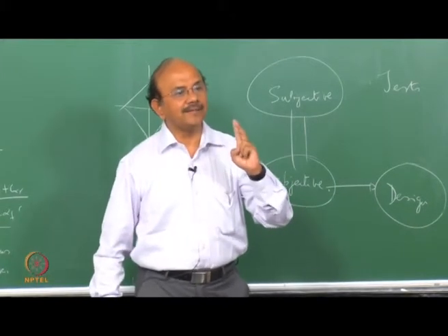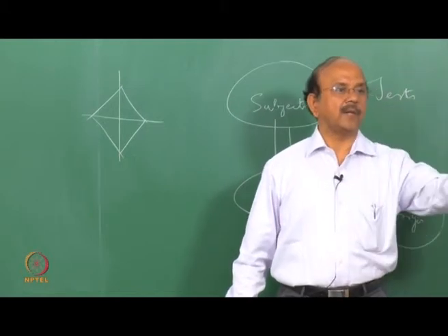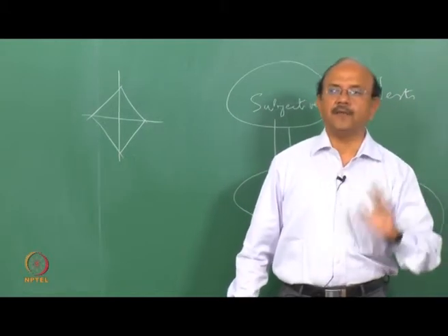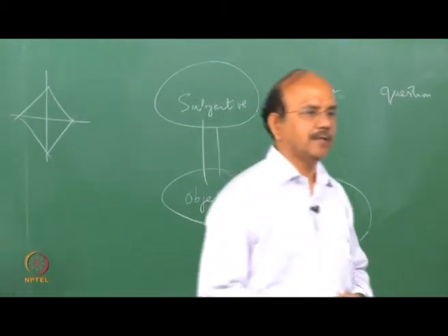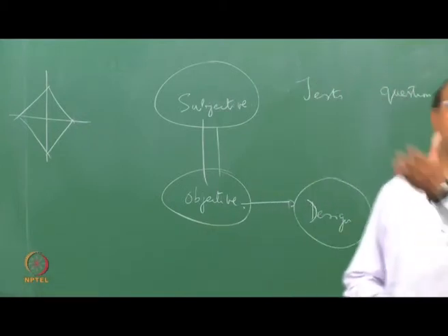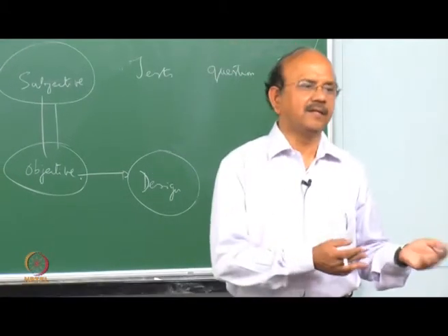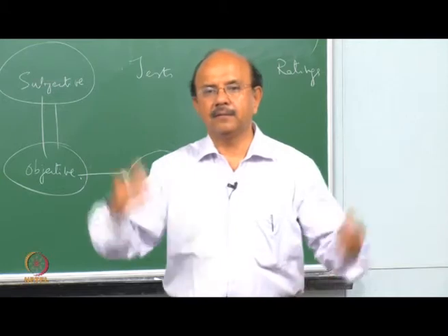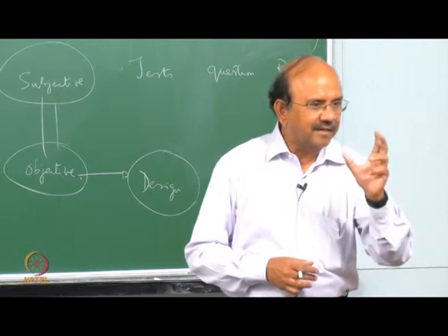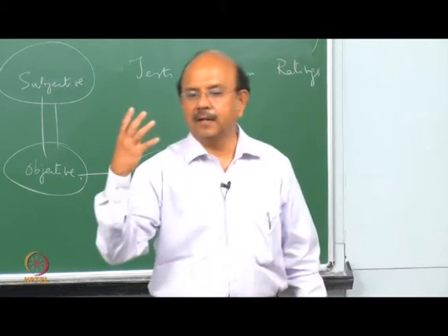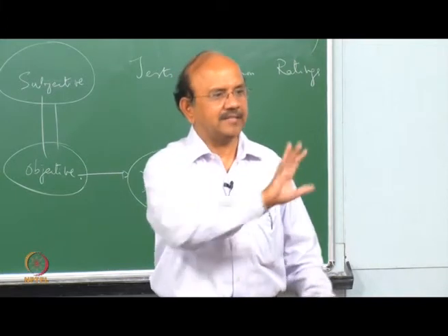This is not like design. Look at this carefully. For example, you did a course on finite element analysis or mechanics of materials. There, in finite element analysis, you were told to calculate the von Mises stress, or equivalent stress, and then compare this with your yield. And then you were told that if it is less than the yield, say yield divided by a factor of safety, or permissible stress, then it's fine. So in other words, there you calculated it and you had a fantastic criteria function which told you, look, compare these two, if they're less, fine.